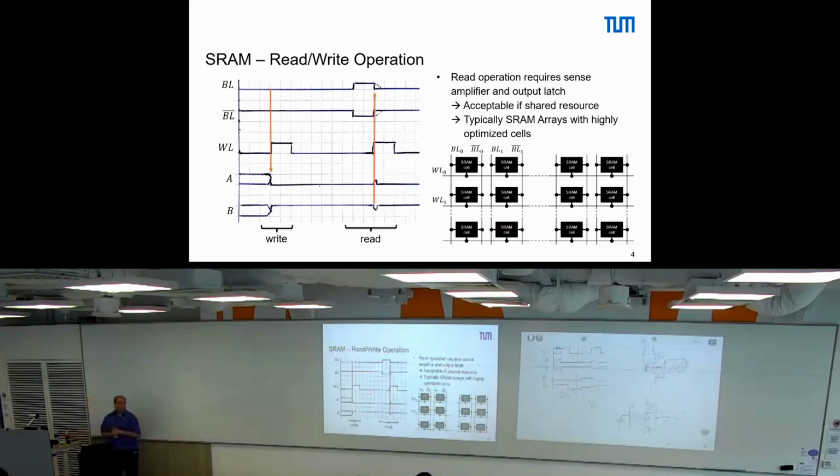So, what can we learn from that? We know we have a memory cell that consists of 6 transistors, pretty small. On top of this, we need a read-write circuit, which has quite some overhead. On top of that, usually you have a register bank for read-write to have the thing synchronized. So overall, you have a lot of interface overhead in order to access the single SRAM cells. And this is why it only makes sense if we share these interfaces.